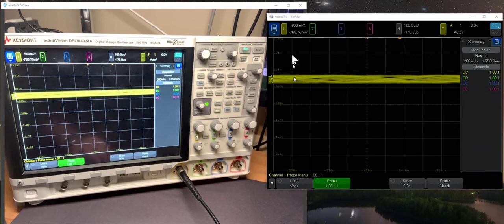Why make your life so much harder to read the values off the front screen? And remember, before you do any built-in measurements or use the cursor, always set up the scope in order to read a measurement with your Mark I eyeball off the front screen. That way you know what to expect from a measurement, and you can compare the value of what you've measured with your eyeball with what the instrument tells you. If you can't read that value accurately with your eye, how do you expect the scope to be able to do it? So one of the important steps after the scope is set up is to adjust the scales.